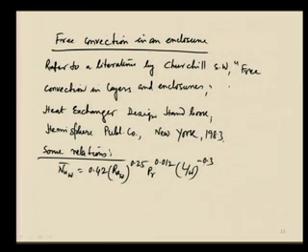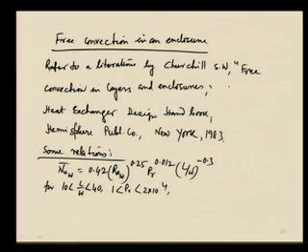So, this relationship is based on the width; it is Nusselt based on the width and Rayleigh based on the width. Okay. So, for 10 less than L by W less than 40, where W is width and L is the length, and 1 less than Prandtl less than 2 into 10 to the power 4, and 10 to the power 4 less than Rayleigh based on width less than 10 to the power 7. So, this is a condition. For this condition, there is some relationship available to calculate the values of Nusselt number.